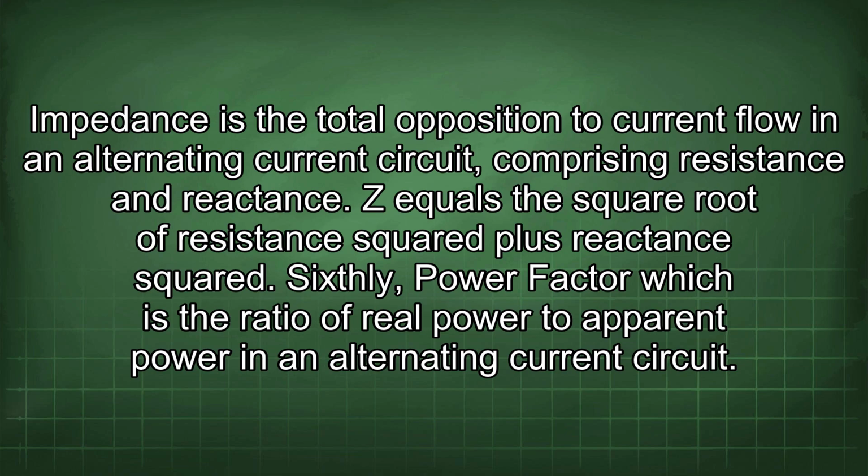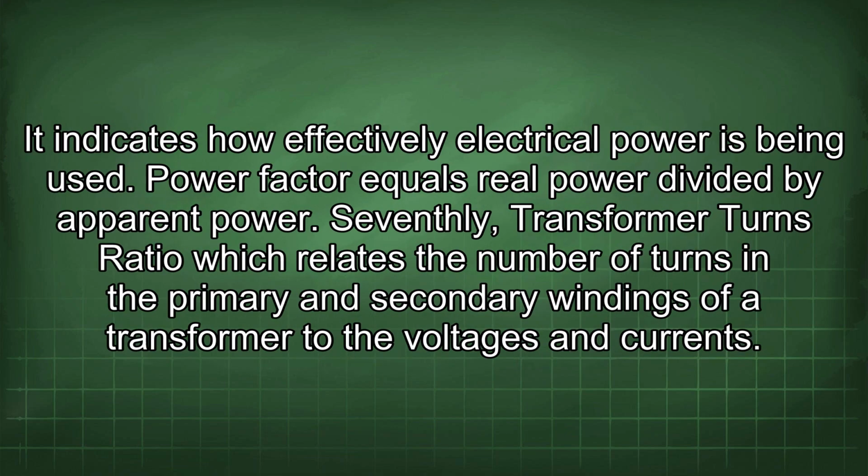Sixthly, power factor, which is the ratio of real power to apparent power in an alternating current circuit. It indicates how effectively electrical power is being used. Power factor equals real power divided by apparent power.